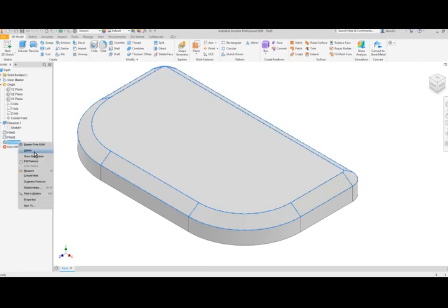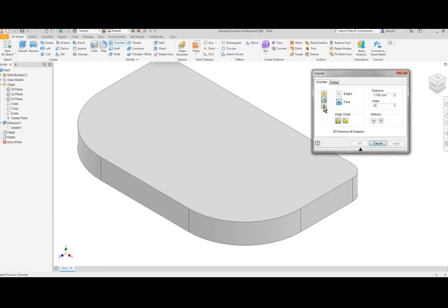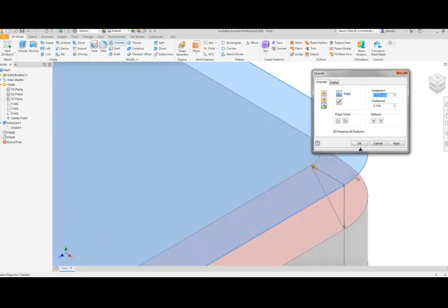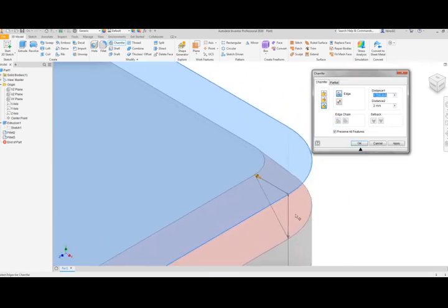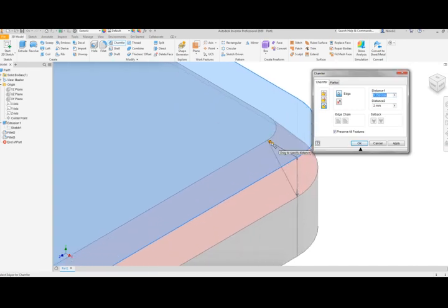Once again, we will delete that chamfer and we will demonstrate the last one. Here's chamfer, and this is two distances. This is all we require to do for this: just simply click on the edge, and then we have two arrows which govern what the size of the chamfer is. So in this case, the active chamfer is the horizontal, so if I drag, it will allow me to, as always, get to a point.